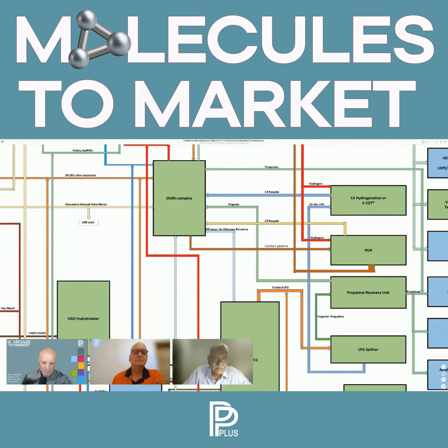Now, one very last important part: when we do the licensor selection, if we have taken a prima facie decision to go to a particular licensor, the licensor selection process is also based on an NIT. So we make a tender document, invite the bids, and then select a certain licensor to give me the basic data, which can be utilized for front-end engineering. So once I have selected the licensor, arrived at the cost estimate, put together a DFR, and confirmed a plus or minus 10% cost estimate, I go to the board to seek my investment approval.